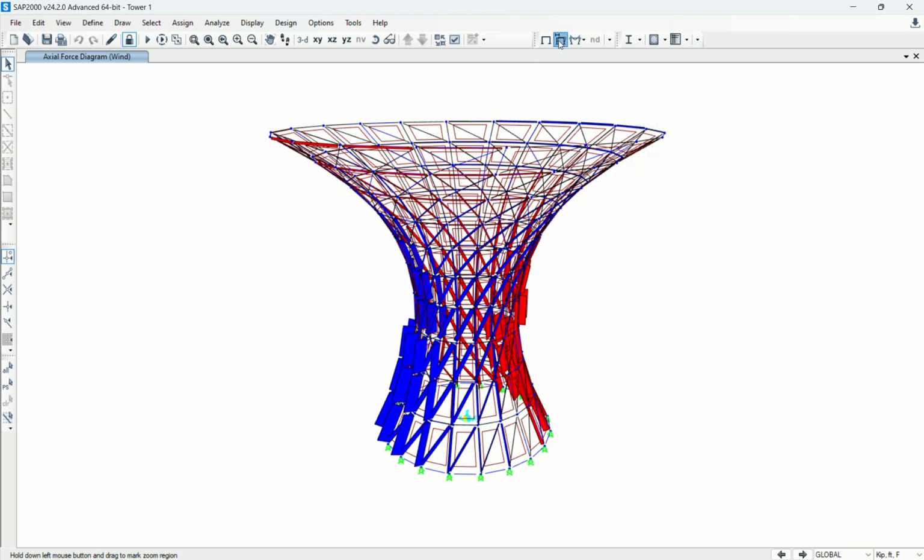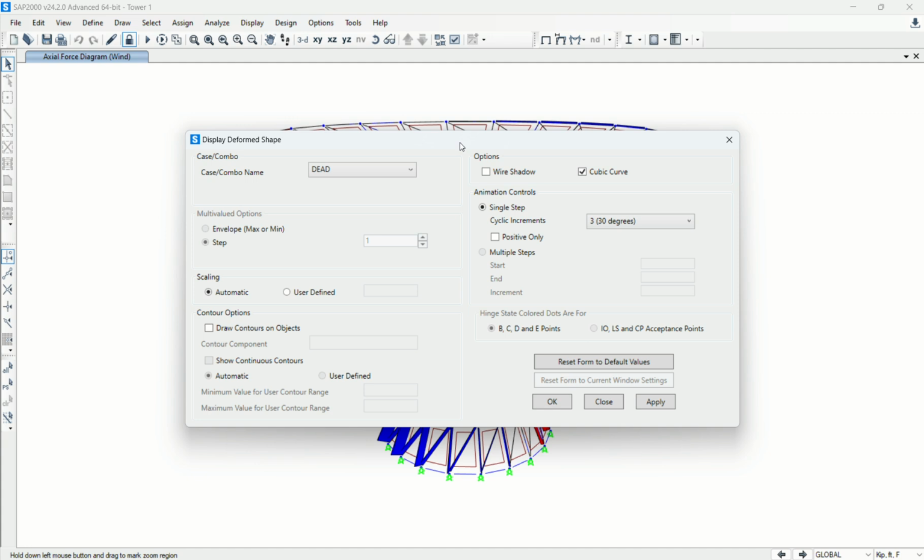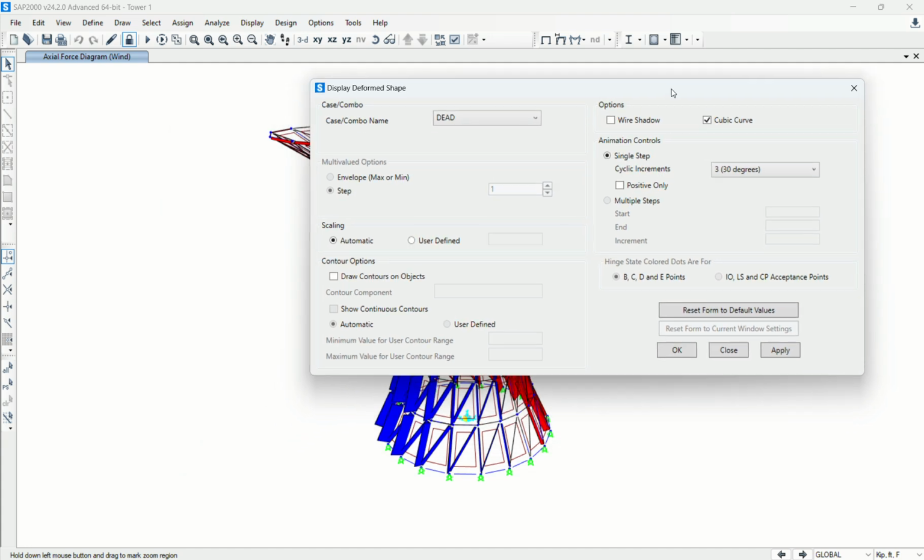So this is a general workflow of how to use the Grasshopper parametric tool to generate the geometry. Those geometries you can export layer by layer, because if you export all together, eventually you need to click each member that you wish to have the same section based upon their group and assign the section property, which is really annoying. So I usually export in separate groups, and by doing that I can easily select all the group and assign the section properties.